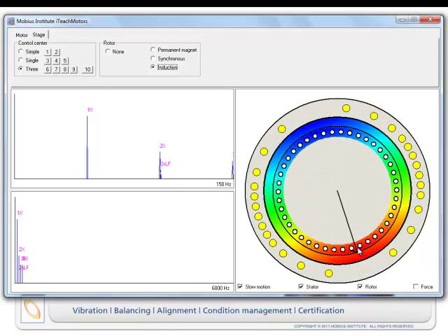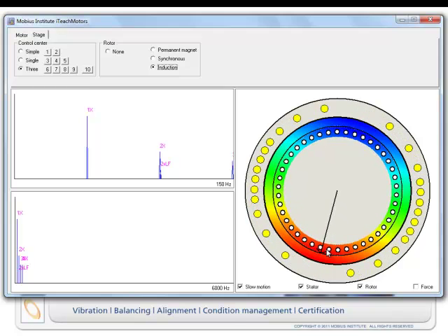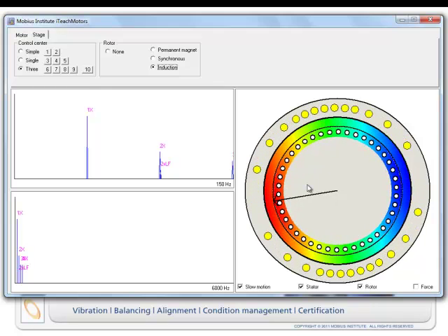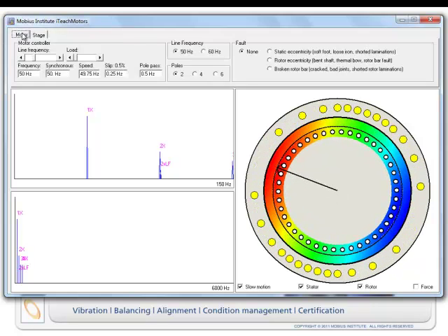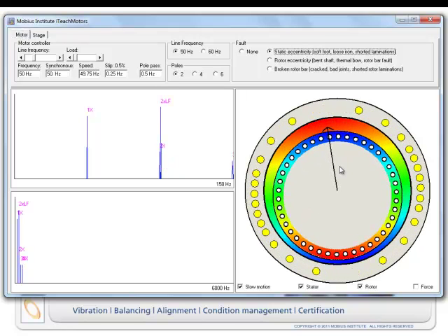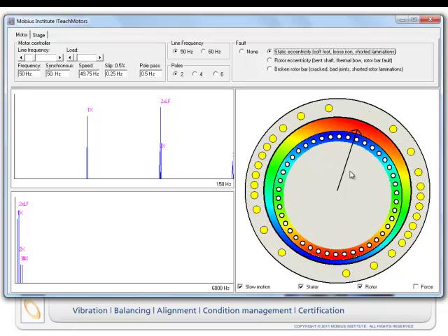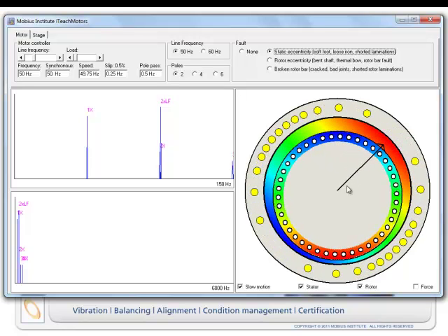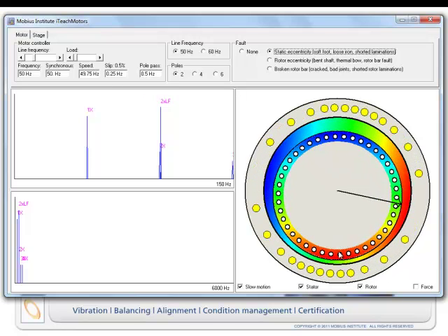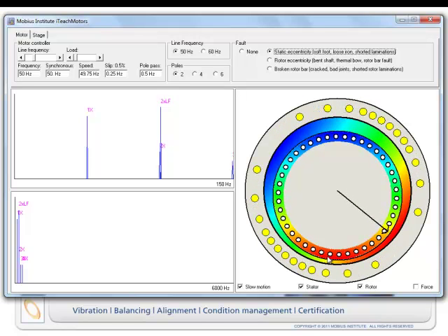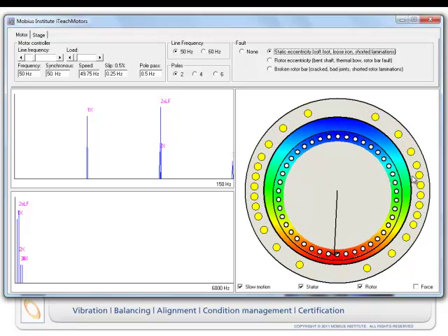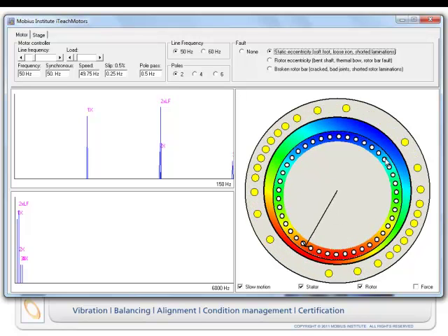In fact, if we look more closely, as that strong part moves over each one of those rotor bars, you can imagine that generates a certain force. And if just one of those rotor bars was damaged in some way, so okay, in one case we've got static eccentricity, so for some reason that rotor is off center, so the vibration is going to be very strong here. These two magnets, if you like, are very strong, and we're going to get that 100 hertz or 120 hertz vibration in that case. Of course, it could be close at 2 points depending on how the stator is deformed.